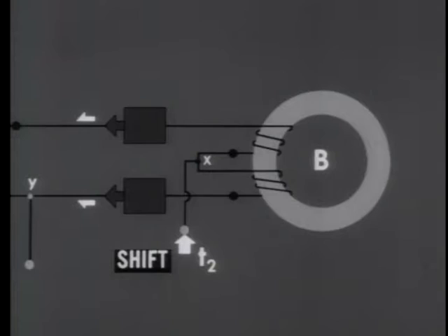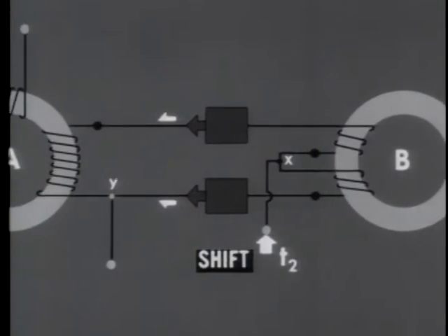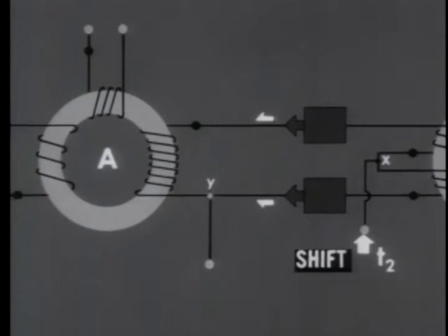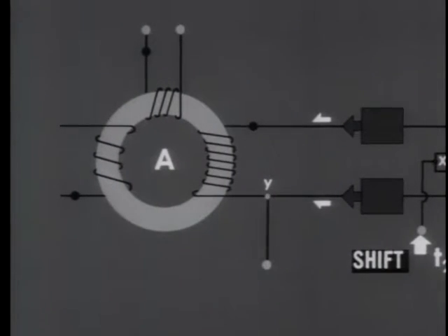The diodes conduct in this direction, and the two branch currents flow toward core A. But the lower branch does not get there. Instead, it flows out of the circuit at point Y. The upper branch, however, does reach core A, entering its output winding as a dot pulse.